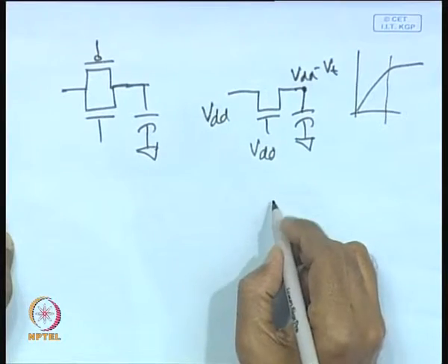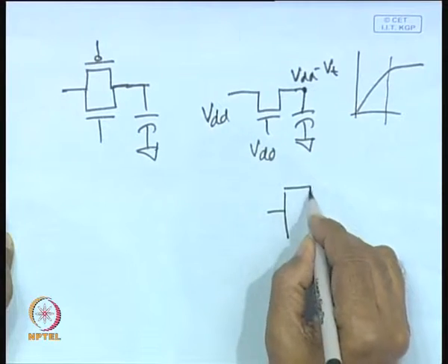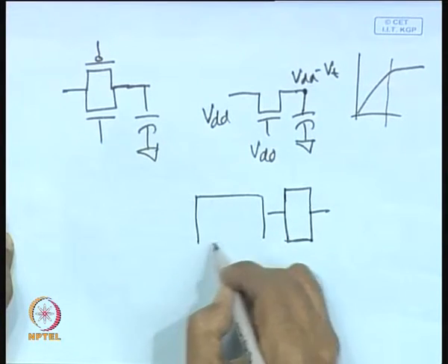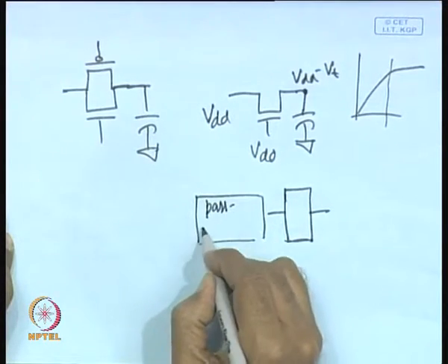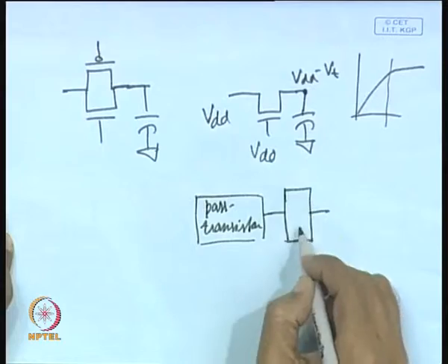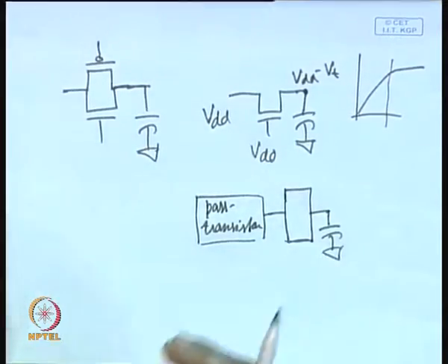That is the reason why, instead of driving through a pass transistor, we put a buffer or swing restoration logic at the output. A buffer is provided. So, this is the pass transistor logic, and at the output of the pass transistor logic we put some buffer, and that drives the capacitive loads. We have seen the pass transistor logic families, DPL, SRPL and various other logic families, or the LEAP family. There we have always seen buffers provided at the output to drive the capacitive loads. So, that problem is overcome by using buffers.